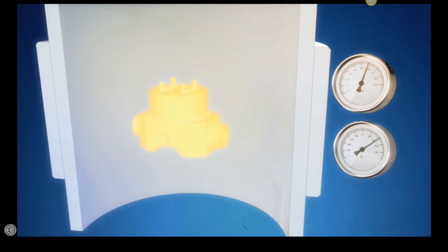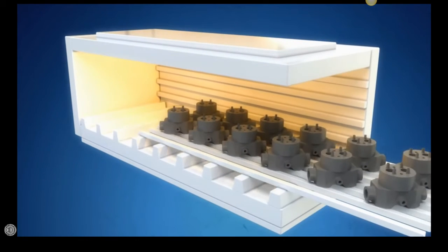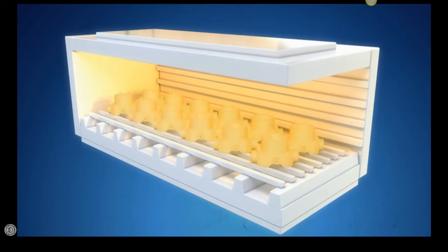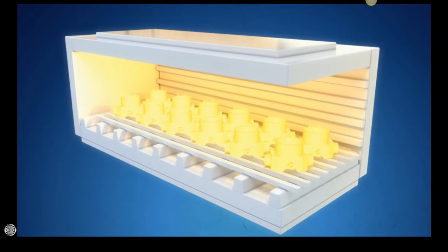To obtain 100% densification, the capsule is exposed to high isostatic pressure using argon gas and applying high temperature. The volumetric shrinkage during the HIP process is approximately 30%. The HIPed material is heat-treated in qualified and approved furnaces to obtain correct properties.